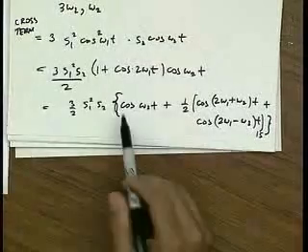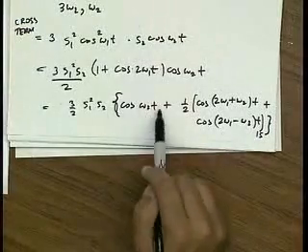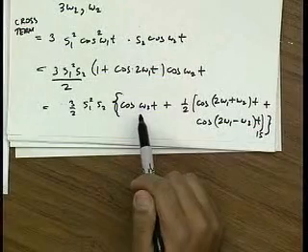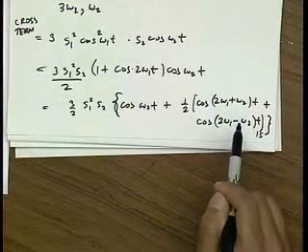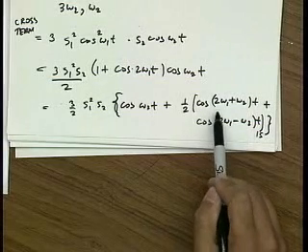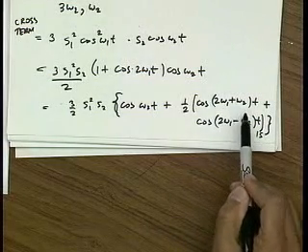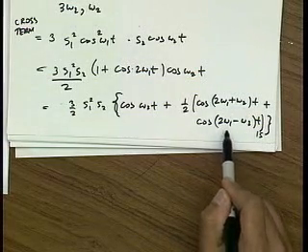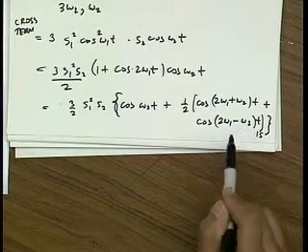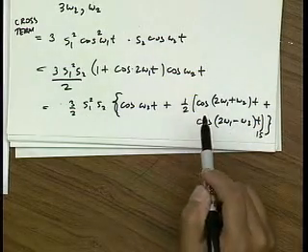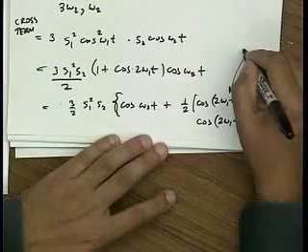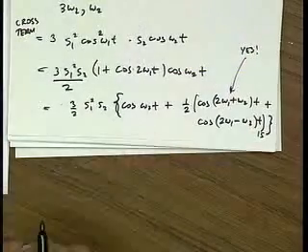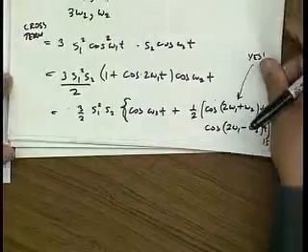Now this is again something we've seen before. This is just more generation of second harmonic. These two terms are the intermodulation terms that we're looking for. We can see that we generate a tone that's 2 omega 1 plus omega 2, it's a new frequency, and 2 omega 1 minus omega 2. So these are the very important intermodulation terms. Just say, yes, that's what we're looking for.